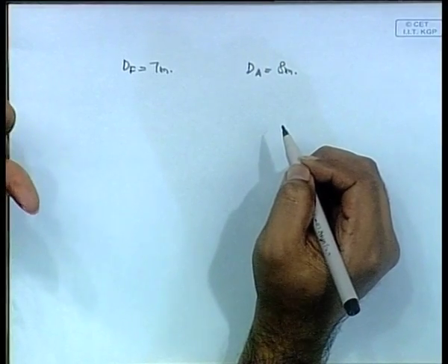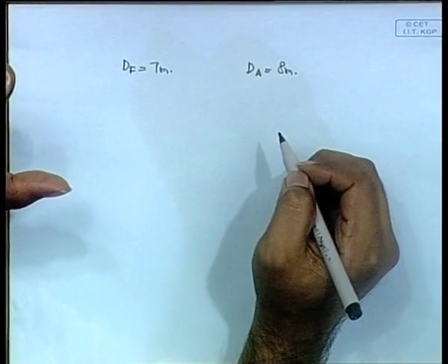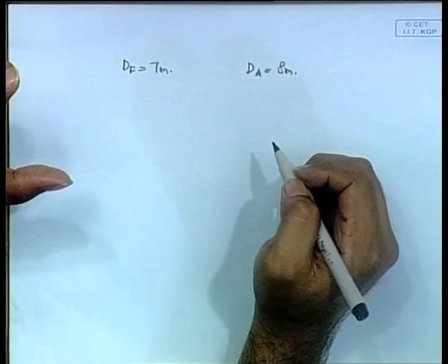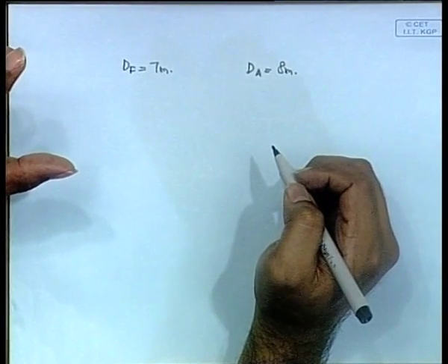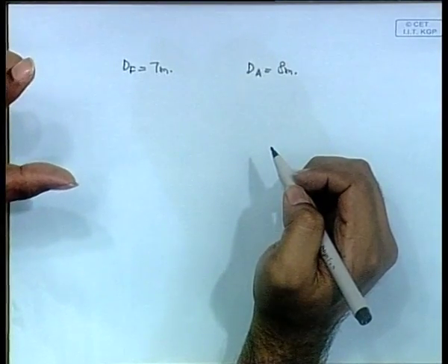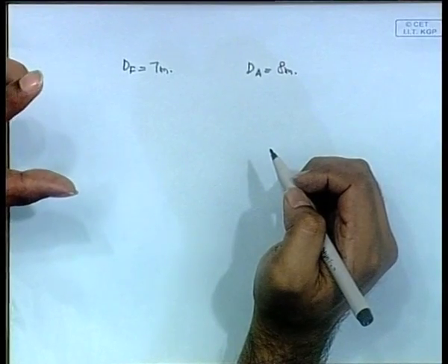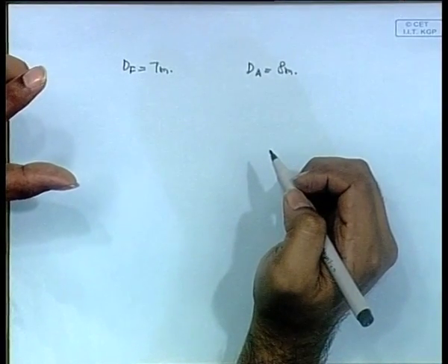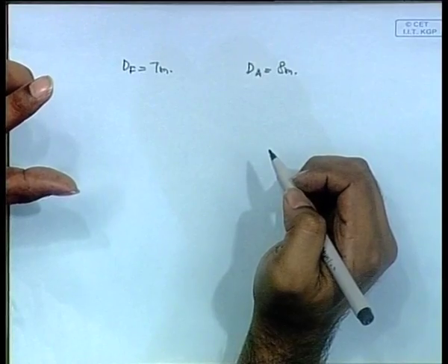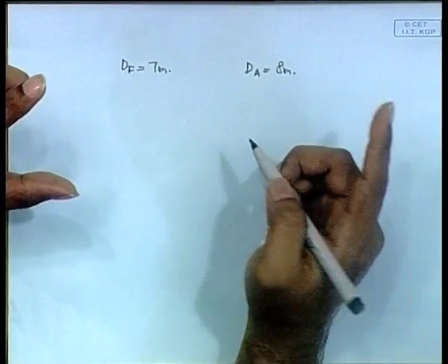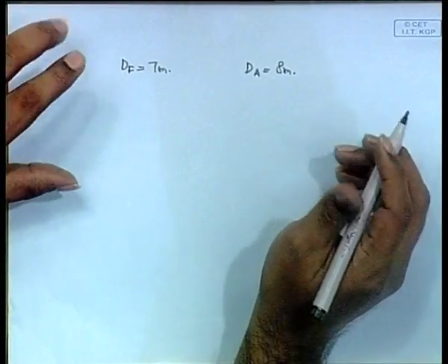Now, you are told to distribute 600 tons of cargo between compartment 1, which is at an LCG of 75 meter forward of AP, and compartment 2, which has an LCG of 130 meter forward of AP, so as to maintain the draft at aft constant. Okay.